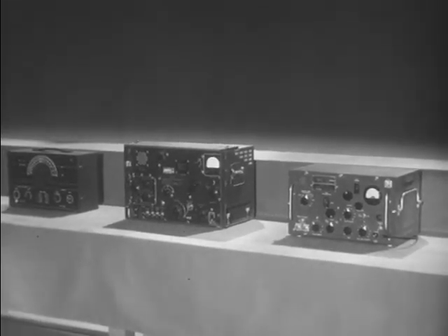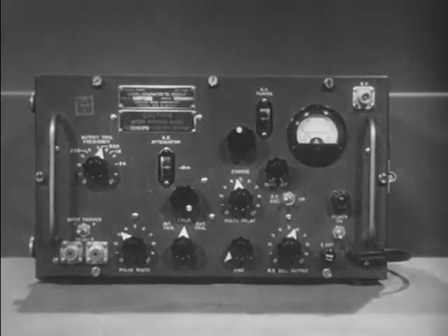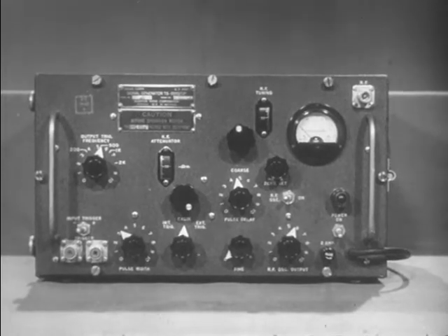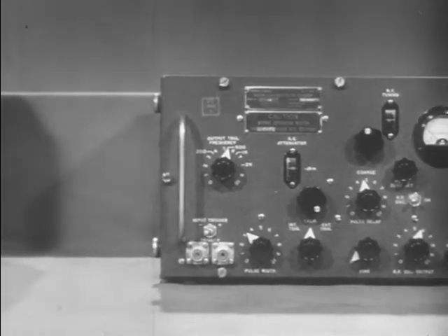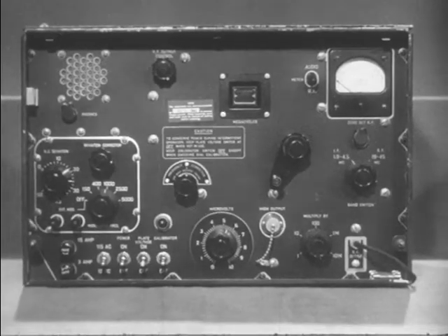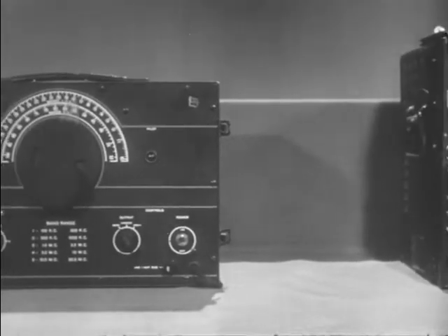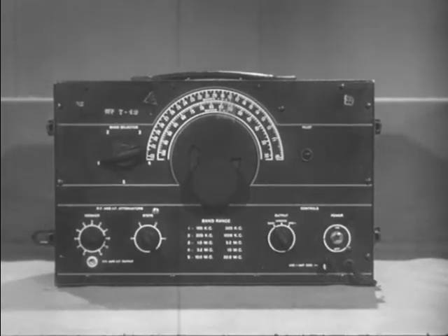A number of signal generators are required for the different ranges used by the various types of signal equipment. This signal generator is designed to operate on the ultra-high frequencies, covering a range from 2,700 to 2,900 megacycles, and is used in radar work. This one is designed to align, test, and calibrate frequency modulation radio receivers. This unit goes from 100 to 32,000 kilocycles. It is a general-purpose amplitude-modulated oscillator covering a wide range of frequencies used in radio work.